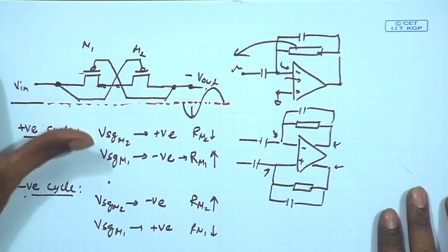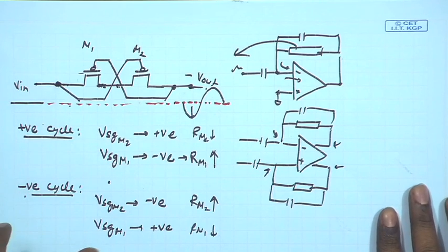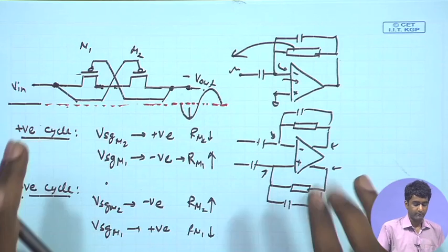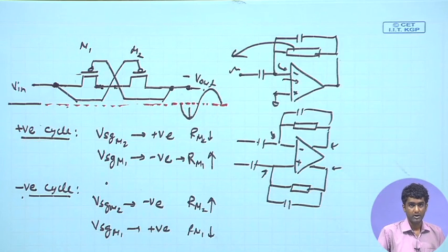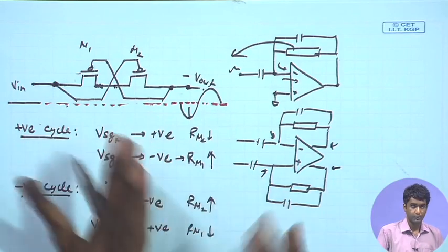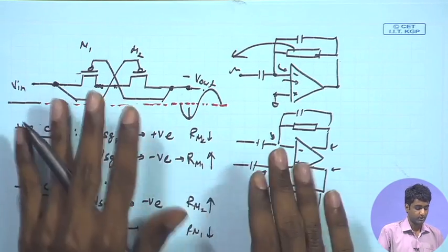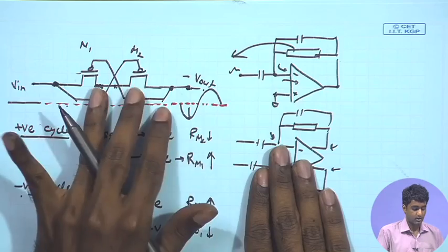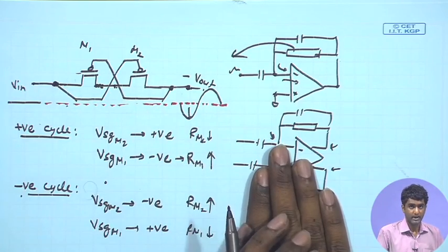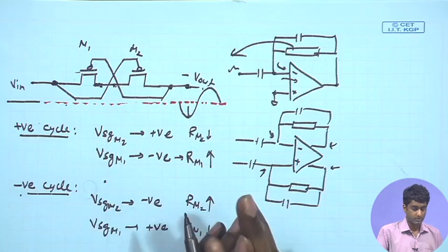Welcome back. As we mentioned, we are going to look into some options for tuning this high value resistor that we just discussed, and the main motivation is that we want to have some options to compensate for the process and temperature variations. So, we will see in simulation exercise also we have options of doing temperature and process simulations. We can run temperatures and different corner simulation to see how much is the resistance varying over a given range